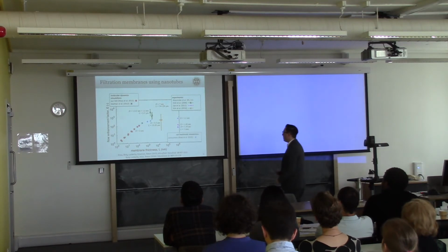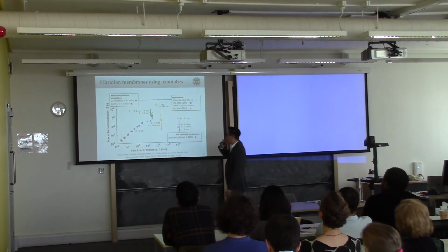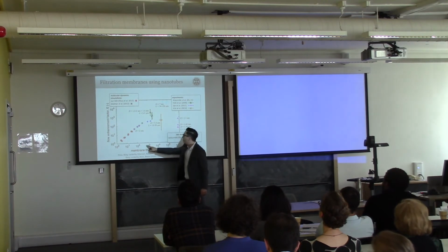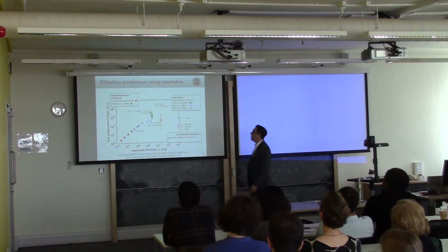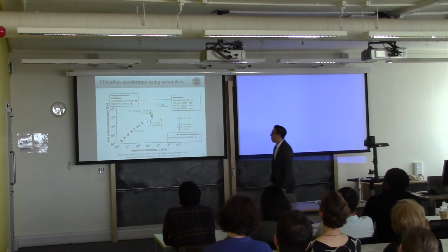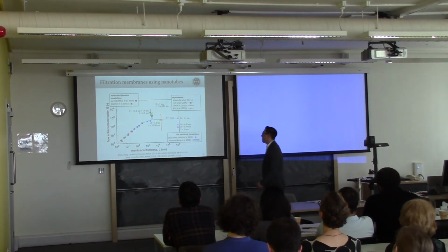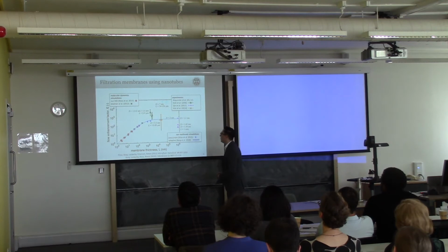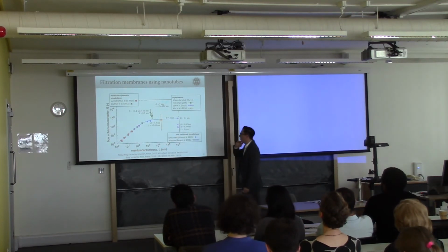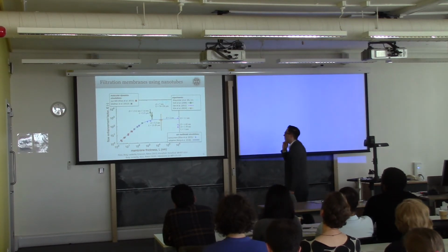So the concurrent method, which I've explained previously, this was our second method, was able to show agreement with our full MD, but also to take us a bit beyond. I want you to know that this is a log scale. So we went a bit beyond, and we realized that we're getting into a noisy period, and we stopped over there. So our adaptive method is the best. We were able to learn from just a couple of concurrent simulations what those flow resistances were, and we were able to make predictions for this particular nanotube diameter.